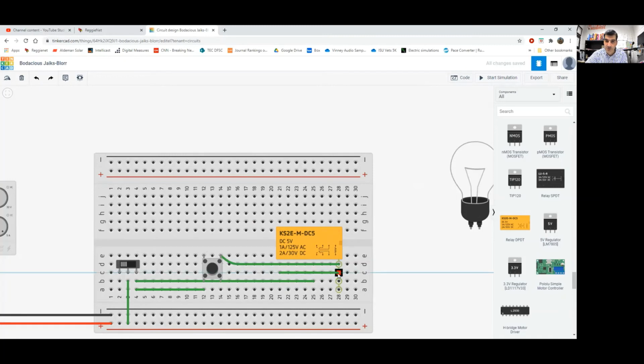So there's actually two ways of energizing the coil, and you can see that in the top rung on Lab 6. It can come from the start push button, like right here, or it can come from the normally open contact, which is right here. Okay, so that is both of the wires to energize the coil.